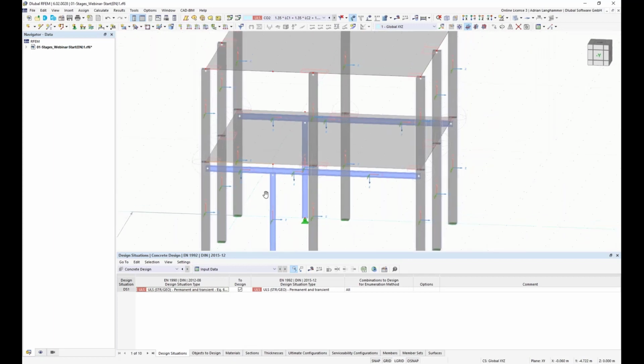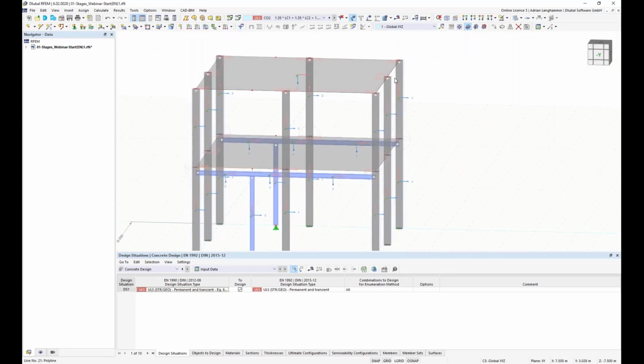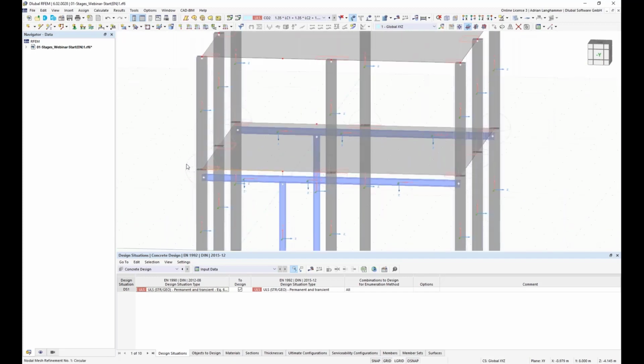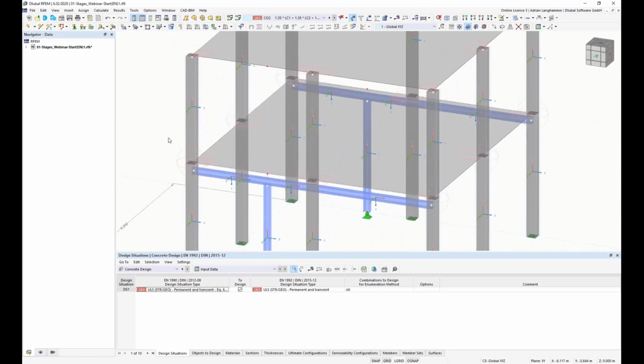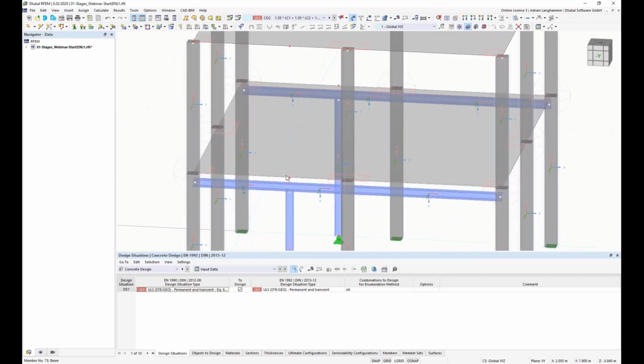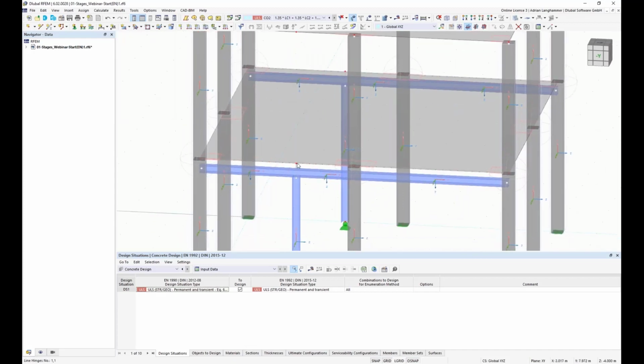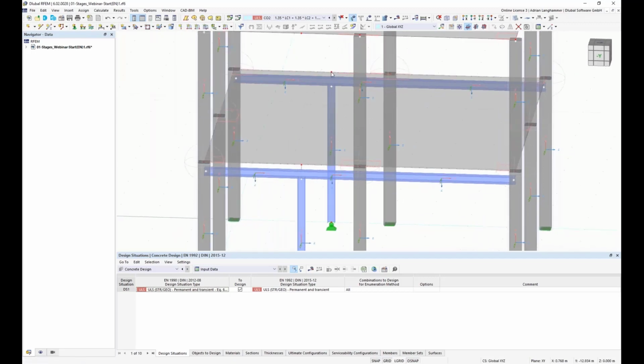Due to the fact that it is an existing structure, there is also above the columns an existing mesh refinement and an existing surface result adjustment, or in RFEM 5 it was called smoothing region. And to avoid later some singularity effects, I can also copy the FE mesh refinement to the new steel column, and also the surface result adjustment.